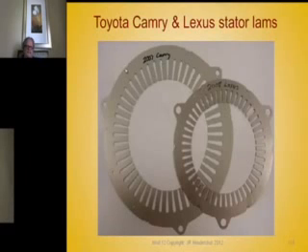But I think what's interesting about this is they have added places for welding this core on the OD. I don't think that's necessary, but they've added it there. They would TIG or laser weld that and melt this little protrusion together there. And I guess they got enough yoke thickness they could do it, but notice they put it over the center of it too. The other thing I find interesting about these punchings is that for mounting this thing to wherever it mounts to, they've added these little ears here with holes in them. And that's a heck of a waste of material to do that. I'm surprised they do that.